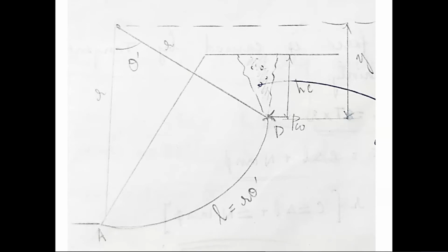But sometimes, just before the slope fails, there is a possibility for a crack to happen here. When it rains, what happens? This crack will be filled with water, right? Imagine there is a crack in the soil here, and that this is your critical slip circle, AD. Earlier, D was on the ground surface, so the critical slip circle was like this. But now I have observed that there is a tension crack in the soil. The soil here has cracked and started to move out.